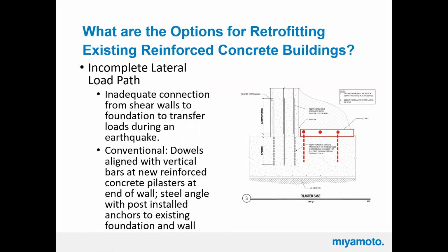But these are, which is what we talk about here, conventional steel angle below slab, post installed, and so on. I think the FRP is probably more compatible with the concrete, maybe more than the steel and the expansion anchors. That's my opinion. It's not based on any fact, and I don't have any research to back it up. That's just my thought from 35 years in engineering. Again, here's the angle sort of approach, or dowels. So there's lots of options to solve these problems, but these are problems we'll see again and again and again.